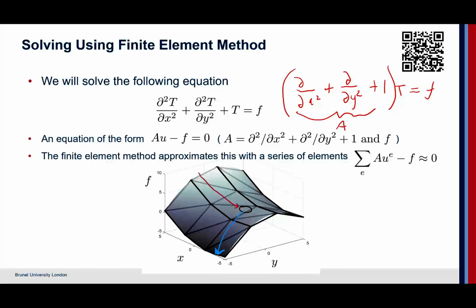Now the reason for writing it in this form is that A will be essentially what you collect together. That's the matrix of all the different coefficients you collect, and that's the K that eventually you end up solving by inverting. So essentially everything in here is the matrix that ends up on the left-hand side of your finite element equations. The right-hand side are the forcing terms. So that's the c term, if you like, in the equations you've got, as well as boundary conditions.